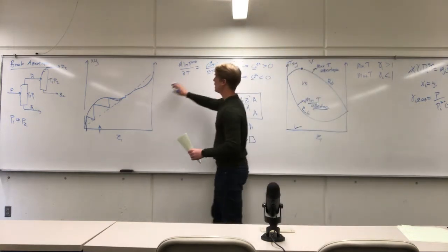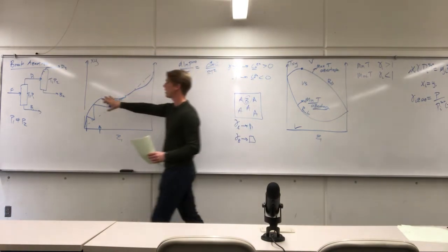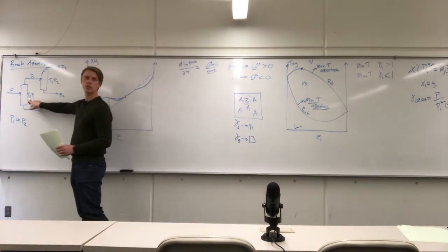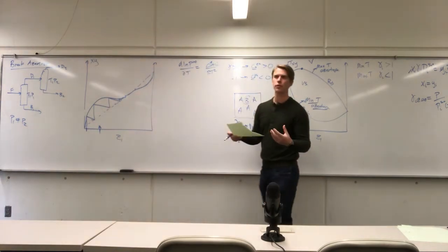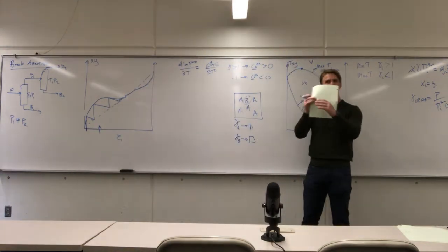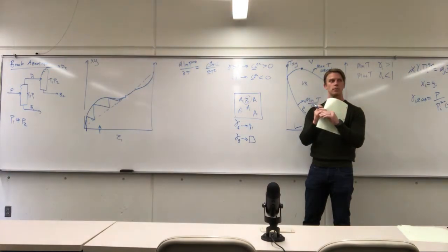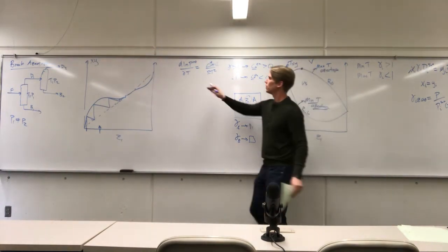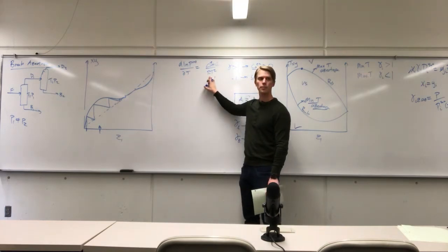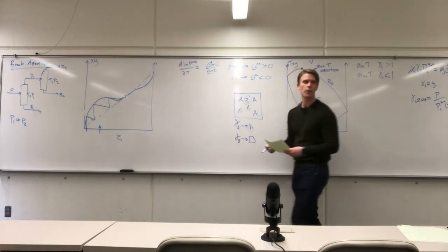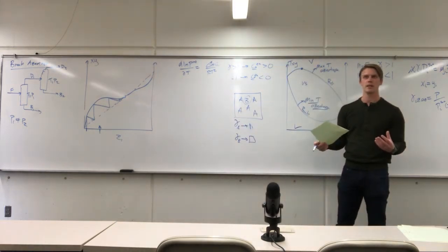So, even if at the composition here, where we reach our azeotrope, the properties of fluid 1 and fluid 2 just end up hitting this nexus where they form an azeotrope, their pure fluid properties are not going to be constant as a function of temperature, right? Unless their critical points are exactly the same, basically.